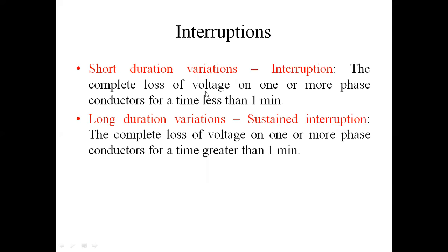Okay, this is very important. Voltage, one or more phases. One or more phases means single phase or three phases. Single phase or three phase, the voltage completely turns off for less than 1 minute is called short interruption. Long interruption is the complete loss of voltage on one or more phases, single phase or three phase, for more than 1 minute. Total voltage will turn off more than 1 minute is called long interruption.